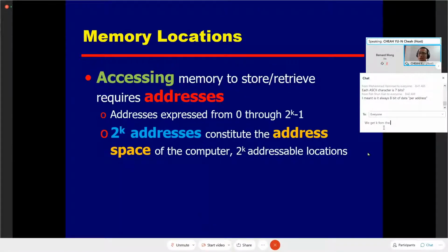In exam questions, the question will give you hints on how many locations there are. Just like the tutorial questions, there are 128 locations, so you need to know that it is 7 bits. In a lot of my examples, I'm just using 8 bits or 7 bits, so you might confuse between the two. But the width length and the number of locations are two different issues.